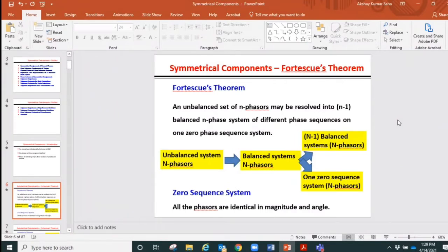And when we talk about this, it's not just that after this, that will come. Because we're talking about voltage or current, we know that in an ideal condition it will be of sinusoidal nature. So we should consider a particular point on that sine wave. We can consider the positive maximum point, negative maximum point, positive zero crossing point, negative zero crossing point, or any other point, and we have to stick to it for all those three phases.